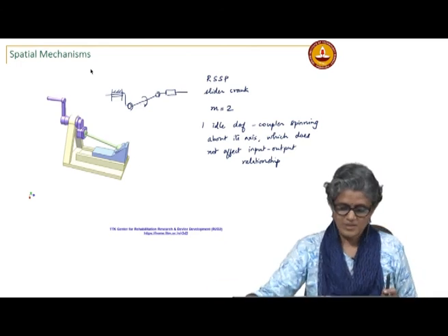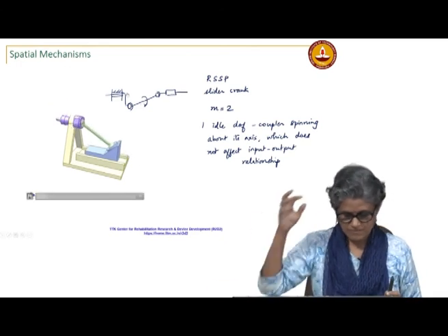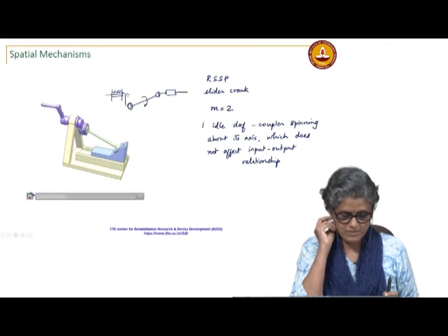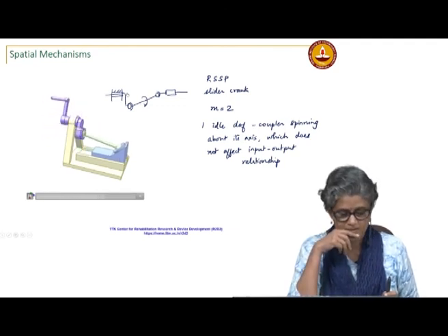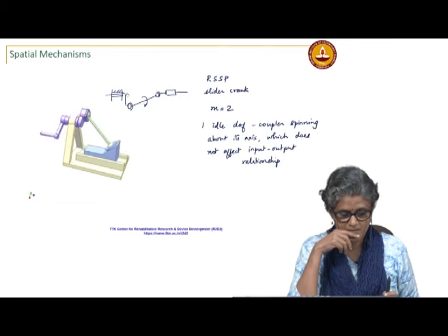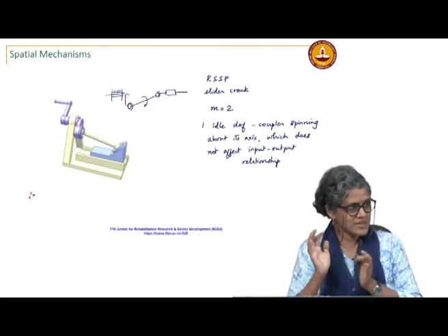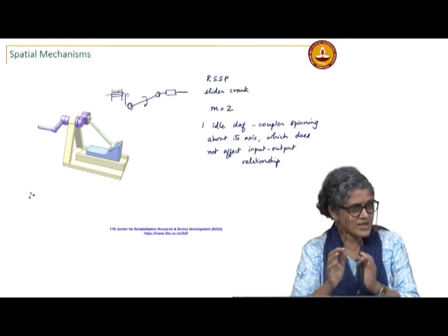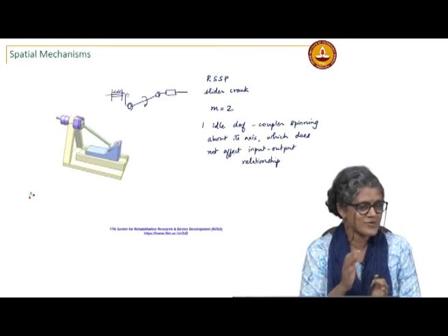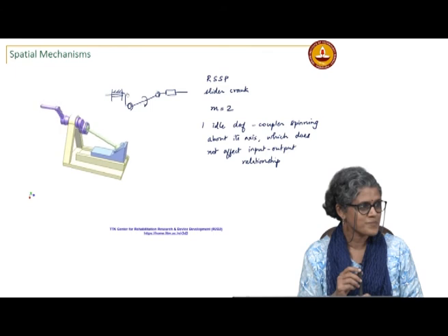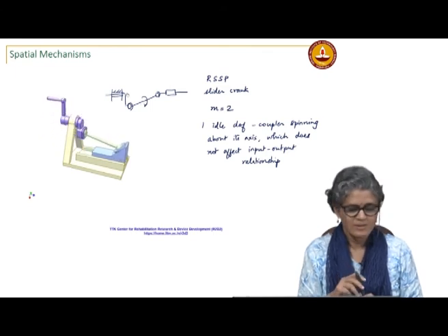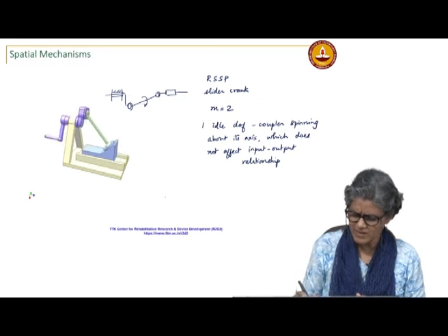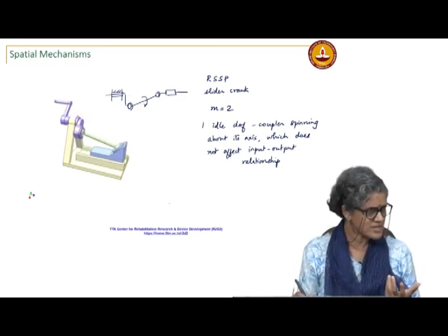Here we don't have a projection like that because the axis of revolute joint is different. If I rotate the revolute joint and make it basically in the same plane, you want to make this into a planar mechanism. You already know how to make a planar slider crank. What are you trying to do? Basically there are still spherical joints. But I just want to rotate that, and if I can do that, I can replace any revolute with a spherical.